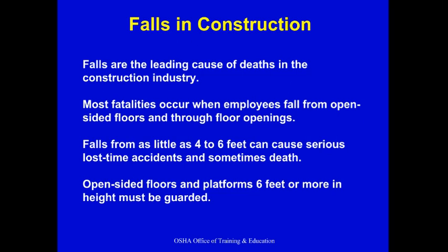Falls from as little as 4 to 6 feet can cause serious lost time accidents and sometimes death. So it doesn't take a lot. You don't have to be really high to die from a fall. And I know you feel like, hey, I jumped 6-foot fences, no problem. I can jump off of a wall and land on my feet. But when you're in construction and you're working, you're not paying attention to the fact that you're falling. Instead, you're paying attention to the work that you're doing. And when you fall, those falls catch you off guard. And it's hard to correct yourself or to respond to that because you're falling.